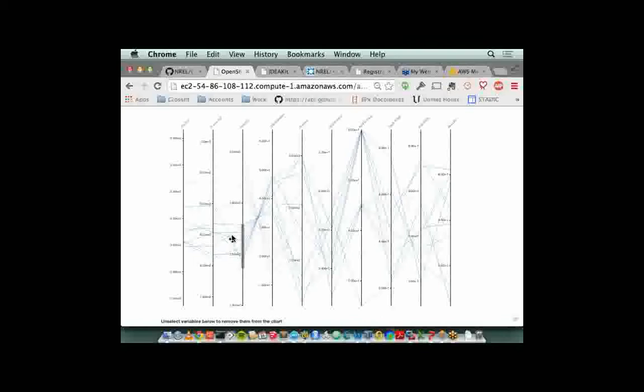You can constrain all different options. You can also move these around. So if EUI is your primary driver, you can put it over on the left, and then you can start to drill in. The different things here were, in this case, lighting power density reductions and wall R value. Just changing the wall R value up and down shows you how many different combinations will meet that specific criteria that you just constrained to.